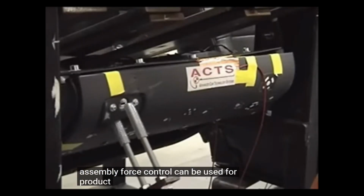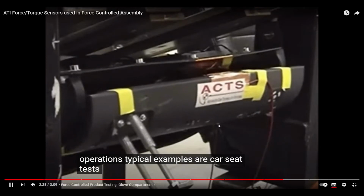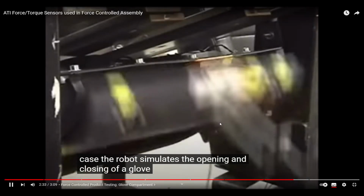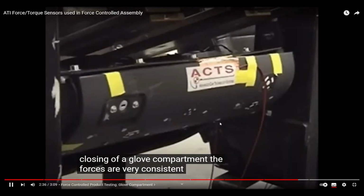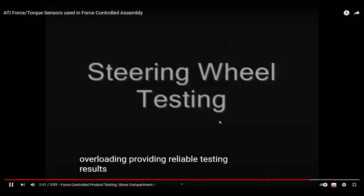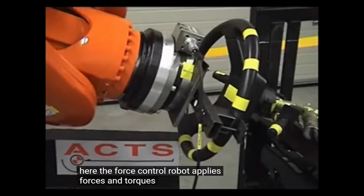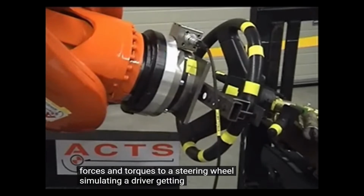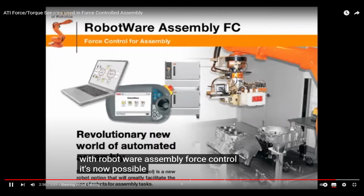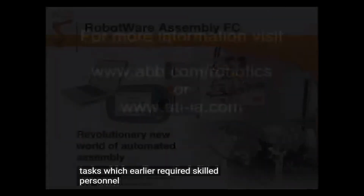Force control can be used for product testing, not only assembly operations. Typical examples are car seat tests or testing of furniture. In this case, the robot simulates the opening and closing of a glove compartment. The forces are very consistent. There is no overloading, providing reliable testing results. Here, the force-controlled robot applies forces and torques to a steering wheel, simulating a driver getting into or out of a car. With RobotWare Assembly Force Control, it's now possible to automate assembly tasks which earlier required skilled personnel.